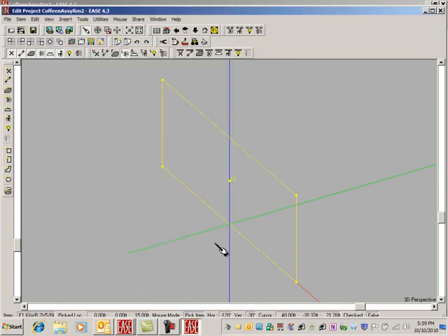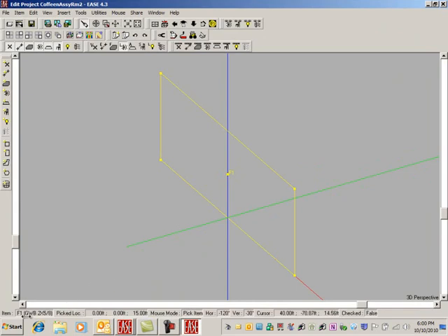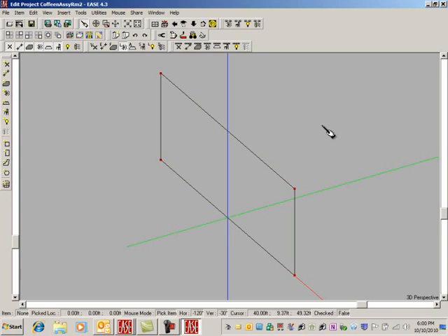But if we're going to move it out there to its position, I don't know how many. We don't need to know the angle really here because we know how much wider it is in the back than the front. And so we could use our junior high school calculator, which I'll get out here, and we could say 2.75 divided by 12 is 0.23 feet. So 79.23 feet. If we made it 79, we'd be about right.